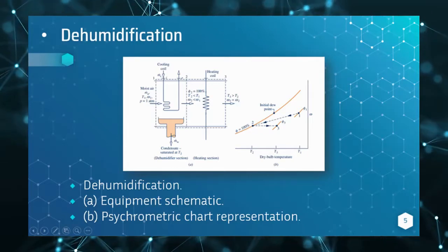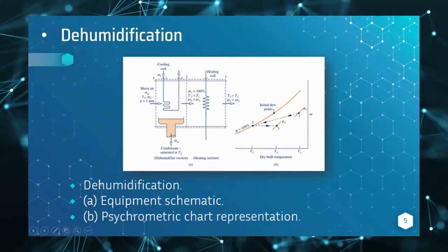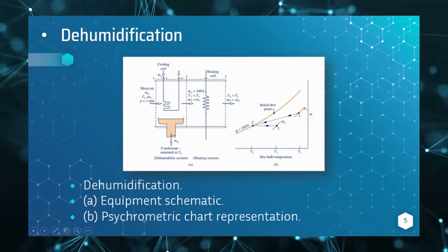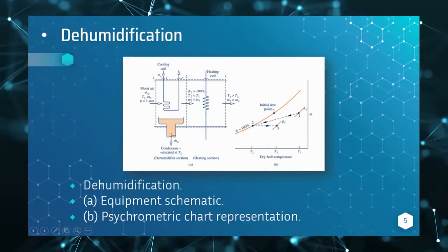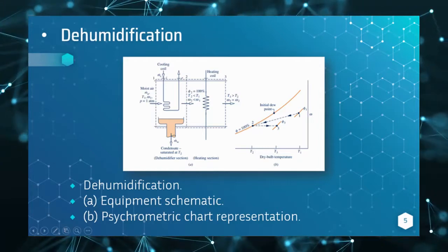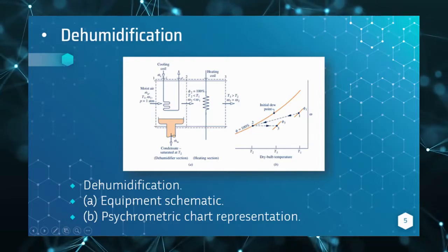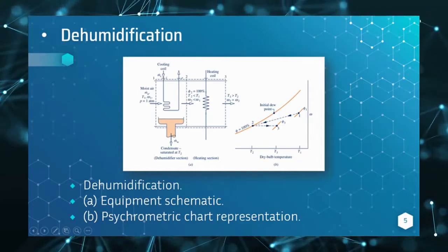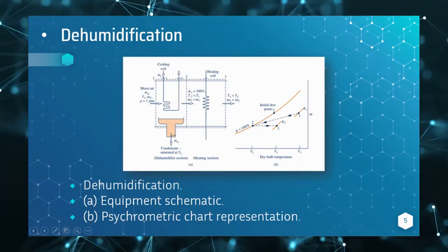Although water condenses at various temperatures, the condensed water is assumed to be cooled to T2 before it exits the dehumidifier. Since the moist air leaving the dehumidifier is saturated at a temperature lower than the temperature of the moist air entering, the moist air stream at state 2 might be uncomfortable for direct use in occupied spaces. However, by passing the stream through a following heating section, it can be brought to a condition, state 3, most occupants would regard as comfortable.